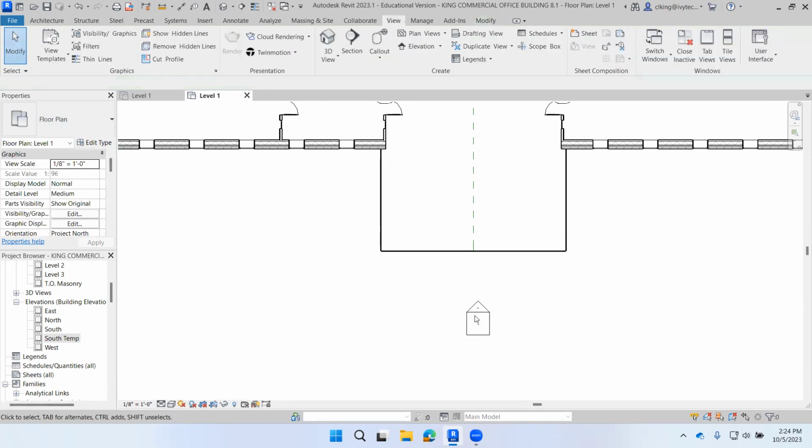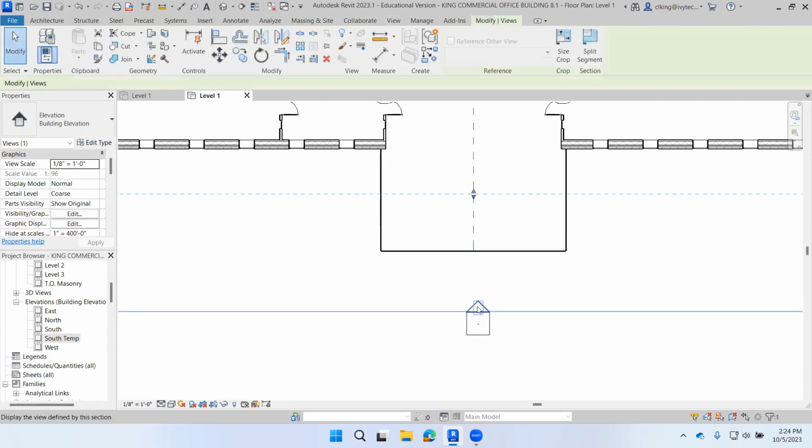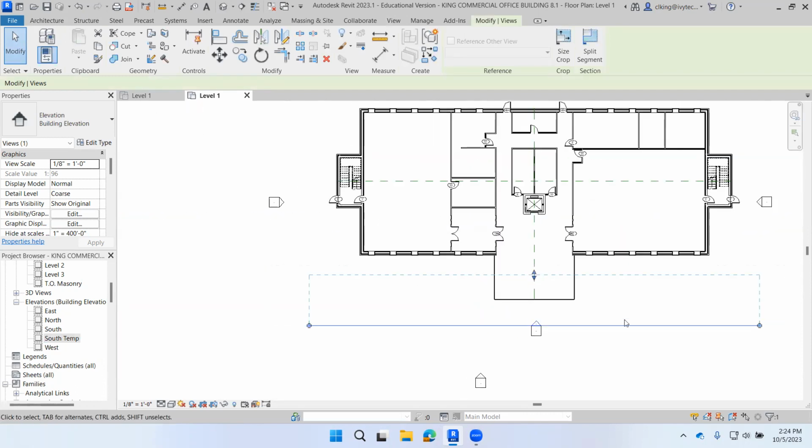Now we're going to deselect it, and we're going to select the pointing portion. And you will see our screen has changed a little bit in its view. In the Properties palette, set far clipping to clip without line, and then click OK. So this right here is adjustment grips to control the view.